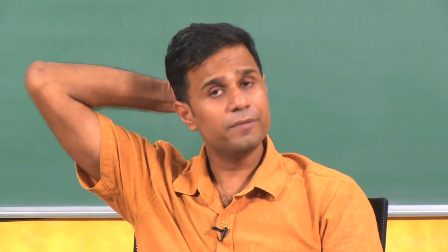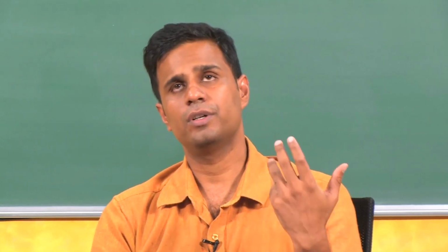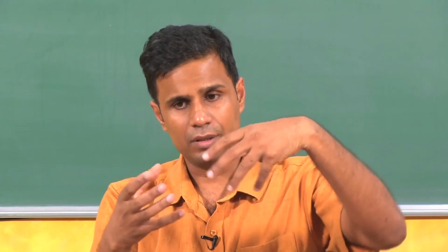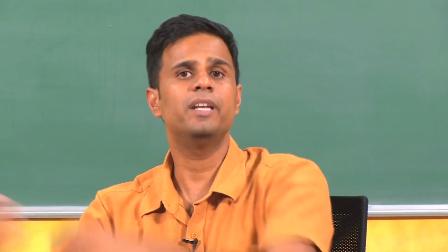While the Kalman filter is one of the standard techniques we use for navigation, what I will be presenting in this series of lectures, along with some experimental demonstrations, is a complementary filter. And the complementary filter is a very simple filter. It is a combination of a low pass and a high pass filter, and we take the signals coming out of these 2 filters and we fuse them in order to get a more meaningful answer to our navigation problem, right.